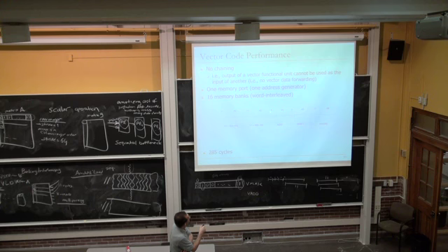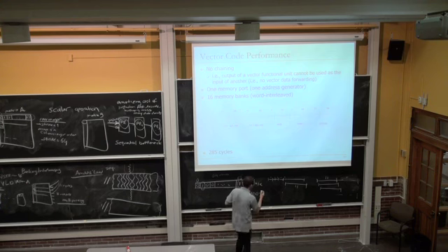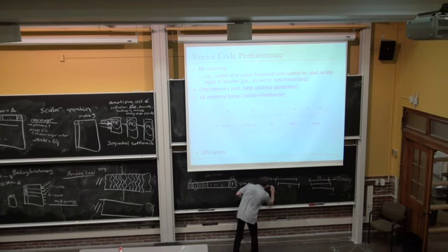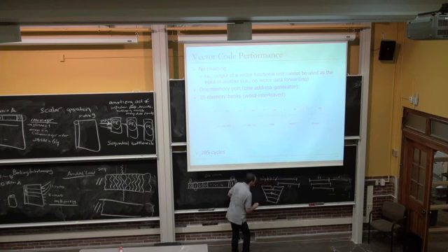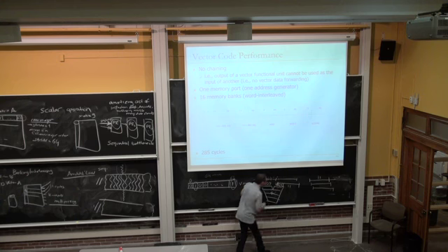So here what's happening is, your adder is pipelined, right? An add takes 4 cycles. You have a single adder, and you have a 4-cycle pipeline, if you will, which means that you can do only one add: addition of vector 0's 0th element and vector 1's 0th element.